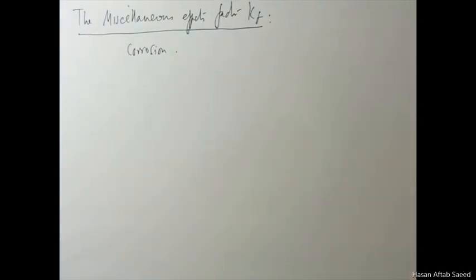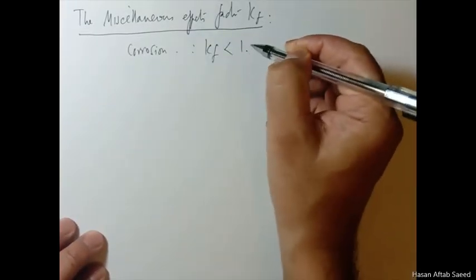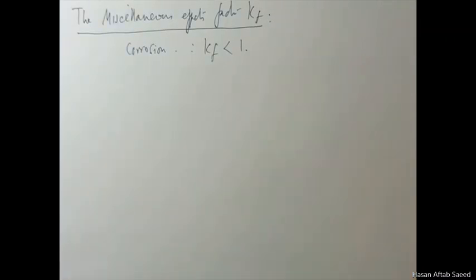It will damage the material along with the stress reversal. Actually, it destroys the bonds. So if the environment is prone to corrosion, one may be advised to have KF less than 1. Not 1, because 1 is for an environment where there is no corrosion, like your test situation.